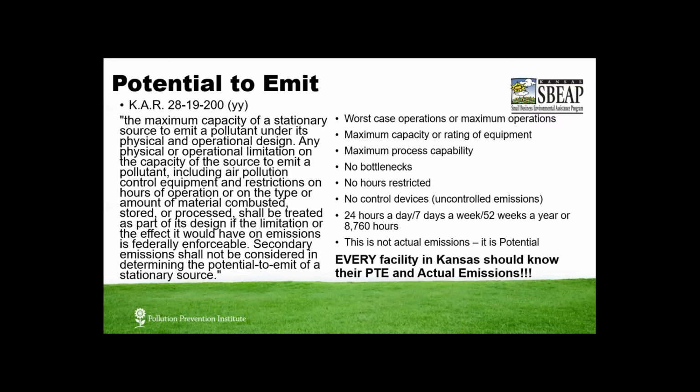The most important emission calculation that can be performed is the potential to emit, or PTE, calculation for individual emission units, emission processes, or facility-wide. PTE is the basis for all permitting actions and for regulatory applicability. For example, the PTE of facility-wide hazardous air pollutants can be used to determine if a facility is subject to a National Emission Standard for Hazardous Air Pollutants, or NESHAP, under EPA's 40 CFR Part 63.